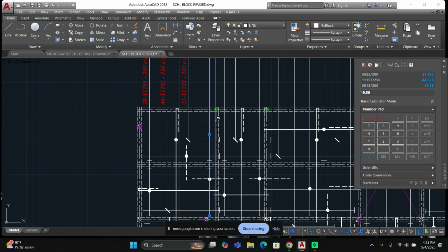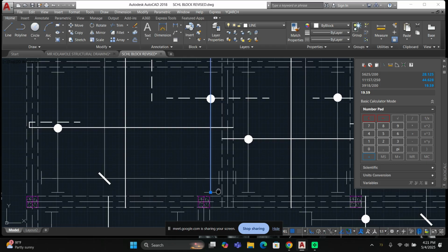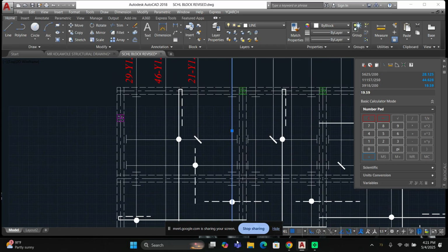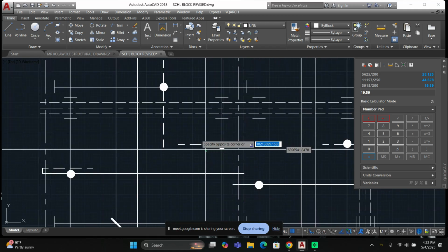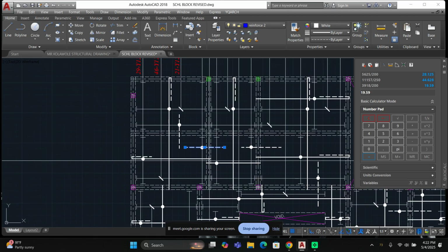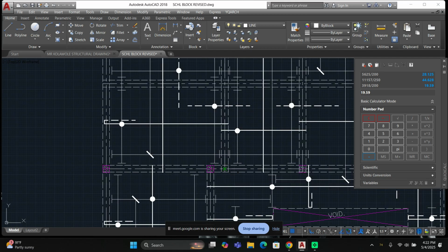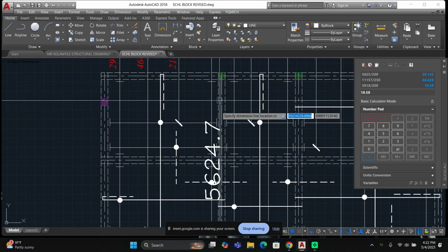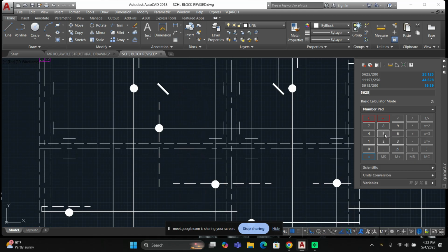You check the third one, the fourth one. You see, it's a vertical one, from this point to this point. Is that not for the top reinforcement, continuous edge? Yes, you see, it's a continuous edge, top 250. You see, 5625. I thought we've done something like that. 5625, but that one is 200, the answer is 29. That one you are dividing by 200, this one is 250.